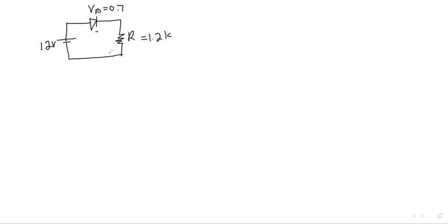For the practical model, let me draw a circuit diagram. When we draw a circuit diagram, we don't include a switch. You must know that in the practical model, the diode in forward bias is a closed switch and in reverse bias is an open switch. We won't draw the switch; you must keep it in mind. Now it's forward bias, and I replace the diode with a voltage source of 0.7. Our Vin is 12 volts, and we know VT is 0.7.